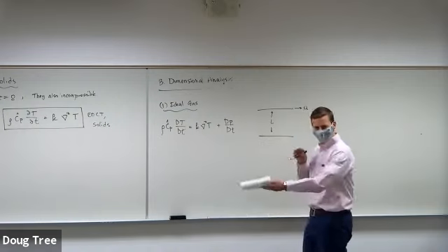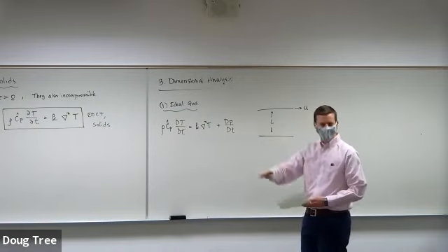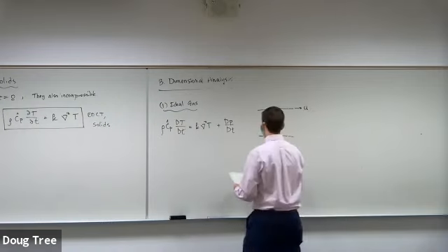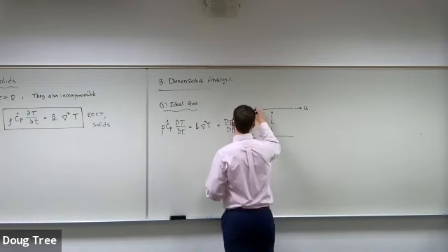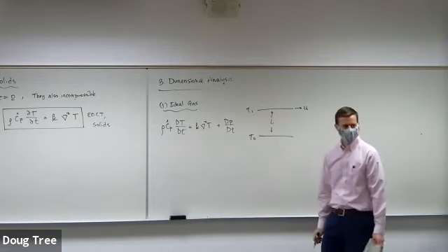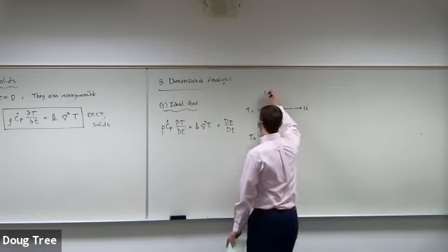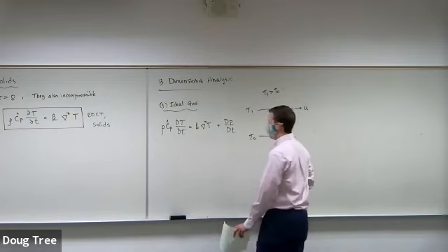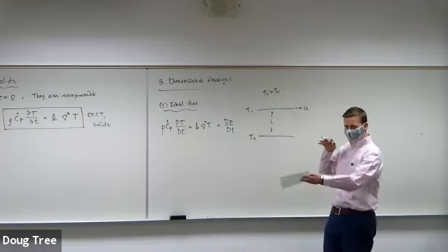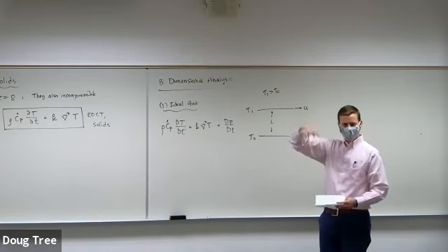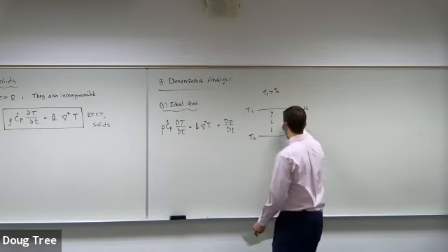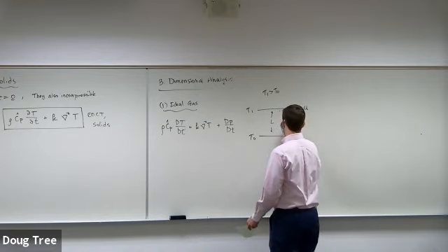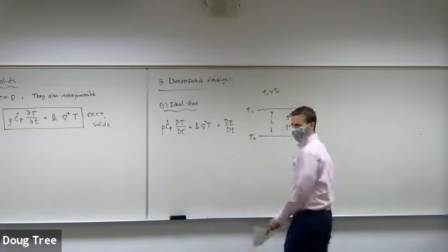Okay, so we're shearing the system, but we're also going to put a temperature difference across it. So we'll put T1 on top, T0 on the bottom. We'll make T1 greater than T0. So we're simultaneously shearing and we've got a temperature gradient. Okay, we're going to say this is a gas in here, which, you know, rho is equal to what, PM over RT. Okay.